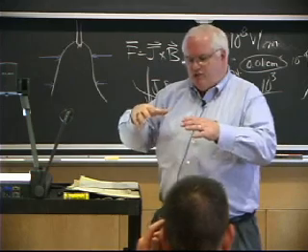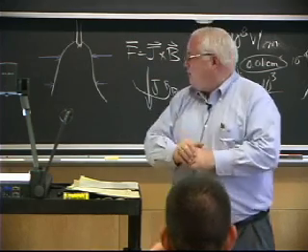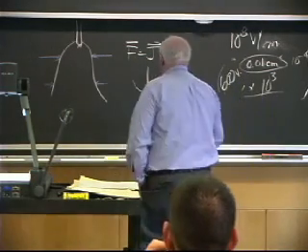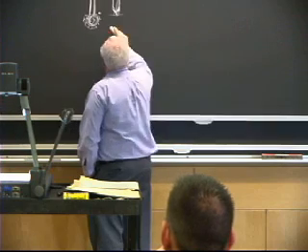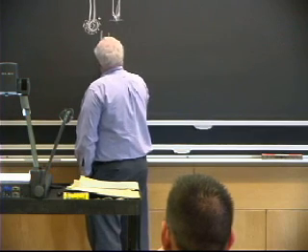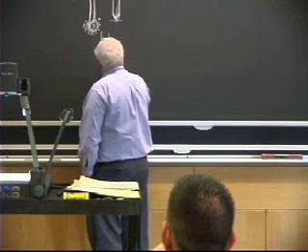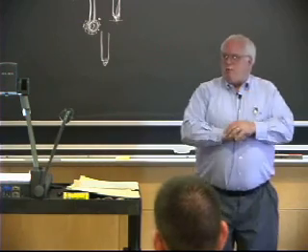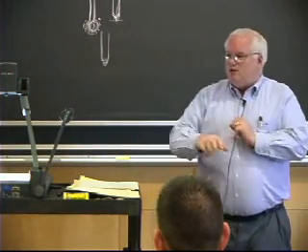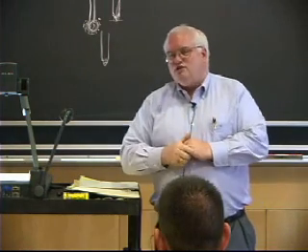And that 500 amps essentially squeezes the drop off so that you don't get this great big drop of molten metal on there. You essentially neck it down so you get something, it might have been molten, but it's somewhat pointed because you basically just squeeze the drop off. Okay, sort of like milking a cow if you want. Okay, just squeeze the drop out.